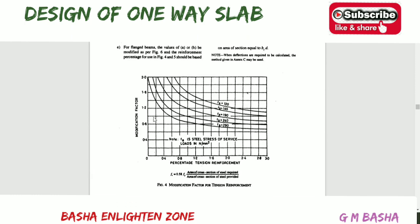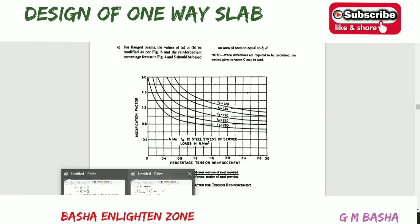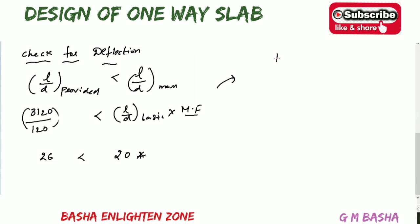See here, if you observe this curve, based on this one you can find out. Here you have to find out the percentage tension reinforcement, and based on that you will get the Fs curve. The percentage tension reinforcement, we already know the formula: Pt equals Ast into 100 by bd. It will already be there in your code book also, Indian Standards.